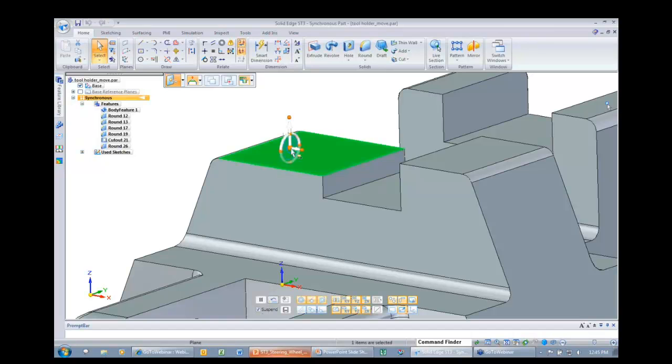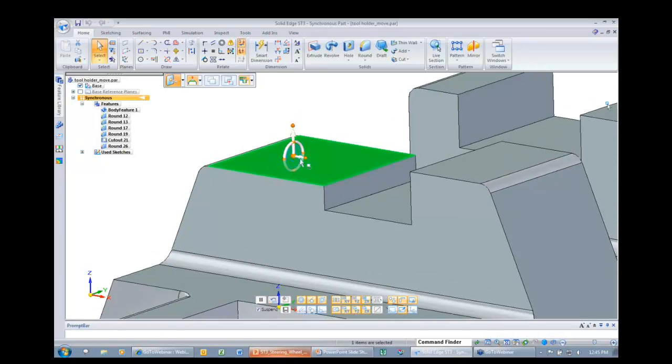If I have that and I just hold down my left mouse button on the origin, you see the 3D steering wheel pop up. This is the primary axis, secondary axis here in the front, the torus, and you see the primary knob and secondary knob at the end, and then the cardinal point. So if I click this cardinal point closest to us, notice how it changes the primary axis towards that cardinal point. So that's an easy way to change the location of that.